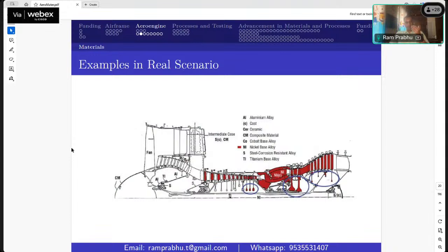What I understand, in Indian projects also, since I have exposure to all the projects, everything from high entropy alloys to intermetallics to aluminum matrix composites or magnesium matrix composites, whatever you research, none of them has gone into a real system so far. Okay, the main reasons are property scatter and process inconsistency. These are the problems, and those problems are still not solved.